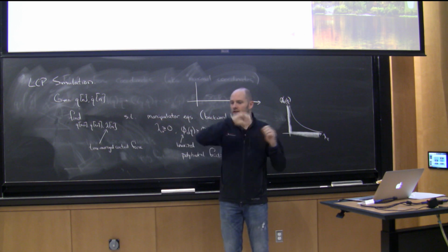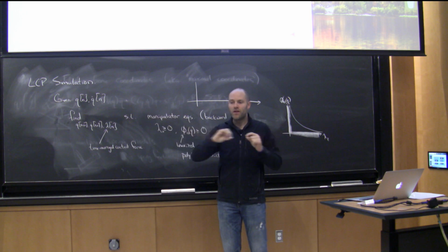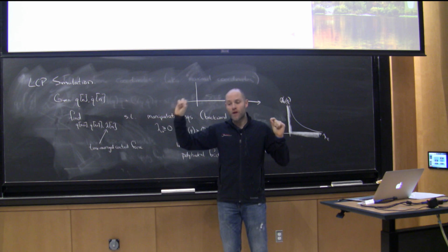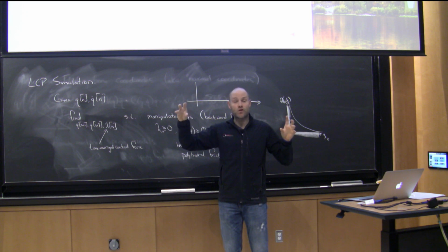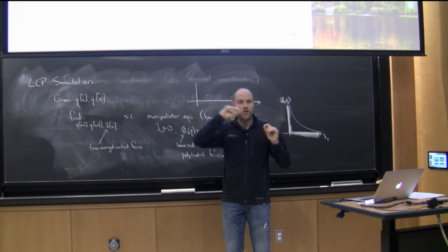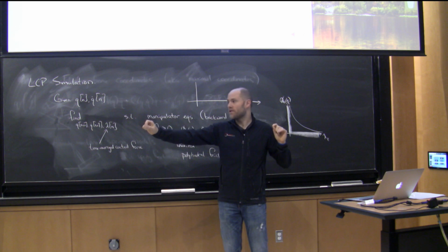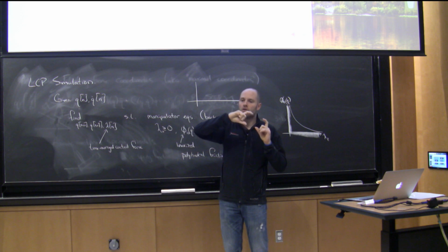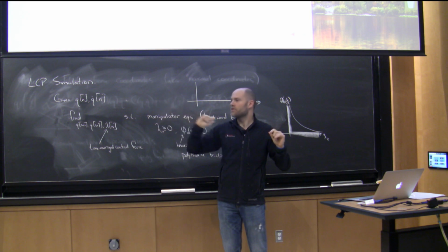If you take a time-varying linearization, you also linearize the constraints. Then if you try to do LQR in the full coordinates, you will fail because the system is not controllable. But if you project down to the constrained coordinates, then you can write an LQR solution along the constrained coordinates, still with all your representations being in maximal coordinates, and your constraint being a time-varying linear constraint.